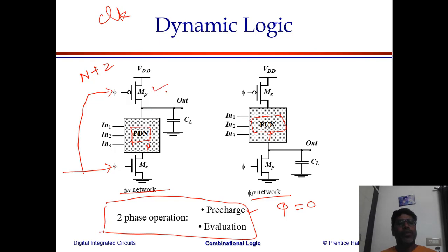The PMOS turns on and it charges the output node capacitance to VDD. That's what we call pre-charge. Pre-charge means by default, irrespective of what is there in my input combination, my output is going to get charged to a value of VDD.